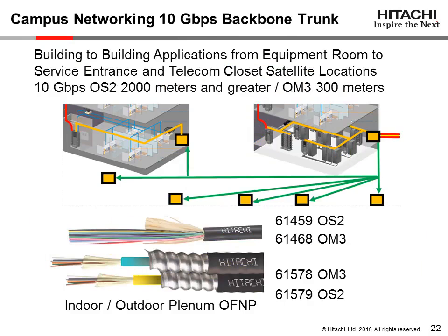From the equipment room, communications are distributed through the campus network. This is the most common area where fiber optic cables are used due to the bandwidth requirements of a high-speed data network and the distance between satellite locations. In these longer distance backbone applications, outdoor rated cables are generally specified for installation in an underground conduit, and Hitachi provides users with armored and non-armored options.